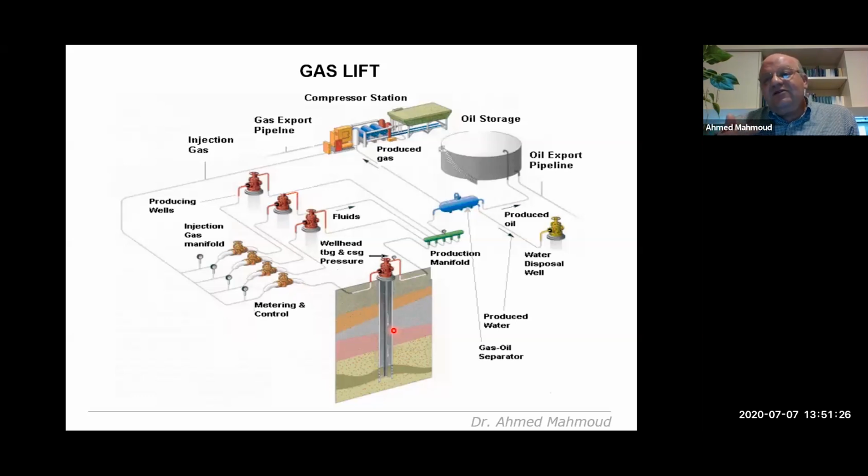And by injecting into weak wells, you actually reduce the hydrostatics. And by reducing the hydrostatic fluid level, you have actually initiated the delta P to motivate the fluid to move all the way to the wellhead. And the first momentum system in gas lift is the economics of it.